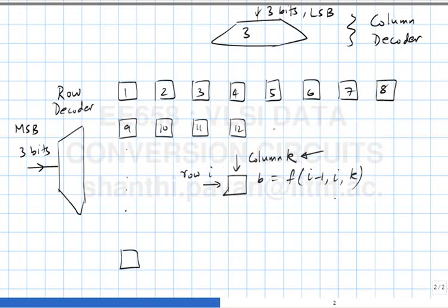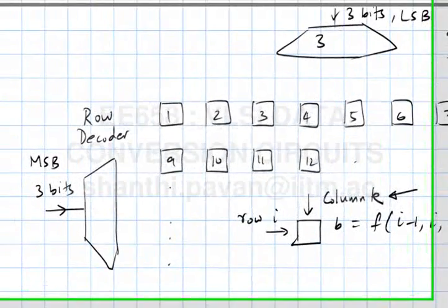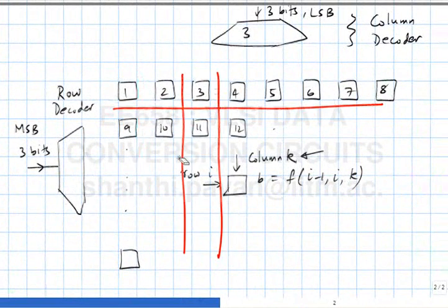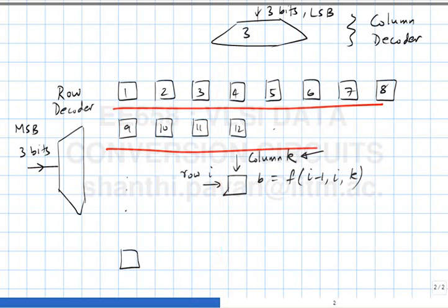And it's important to generate this B bar properly, because if there's an overlap between B and B bar, that's when you're okay. If at any time during the entire cycle you find that the tail current node is dipping, then you're in for trouble. And you should propagate the clock. I guess you either do it this way or this way.